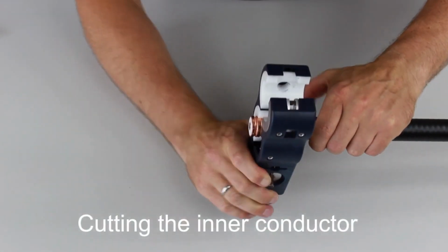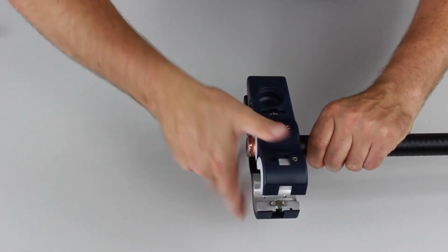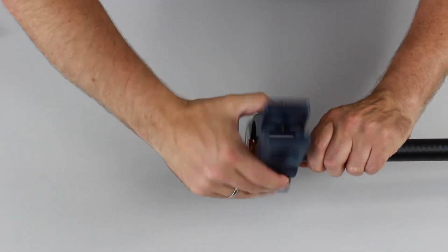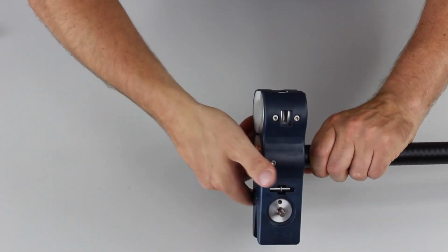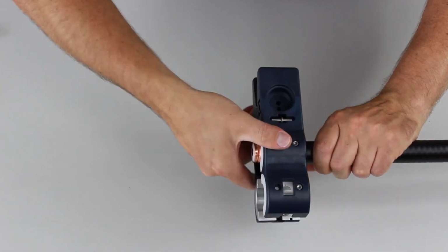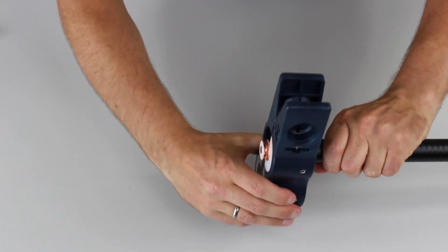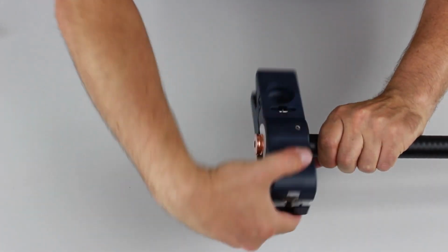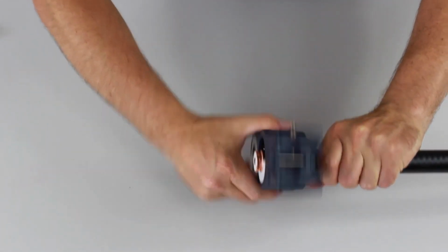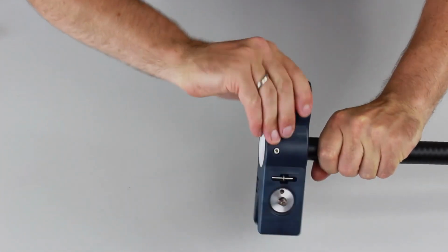Do not apply any pressure. Use the tool's spring force to apply the tool and rotate it all the way around the cable. Only hold the tool at the bottom end. Only turn the tool until you have cut through the outer conductor. From now on, hold the tool at the front end and apply light pressure until you have completely cut through the inner conductor. If this is the case, use pressure to cut around the cable again 2 to 3 times to achieve the sheath cut that is required for the right connector assembly.